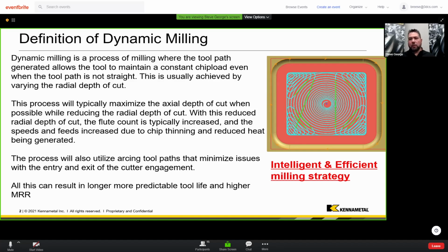Well, the cutting speed on the same type of cut is directly influencing temperature. So if I've got another way to decrease temperature, then that can let me increase my speed. And if I can increase my speed, I can increase my feed rates and look to get more productive. And that's where this starts to come into play.